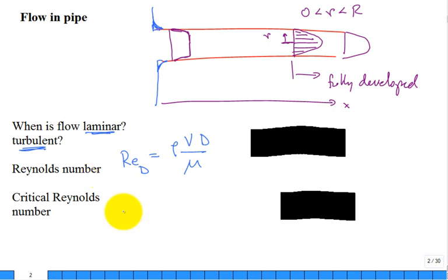So what is the critical Reynolds number? Around 2300. Again, it's just a number, it's rough numbers. Some people put 2100. Some people just round it off to 2000. Can you have it become turbulent at 1800? Well, yeah, if you have some perturbation in the system, if the wall of the pipe is shaking or moving, yeah.